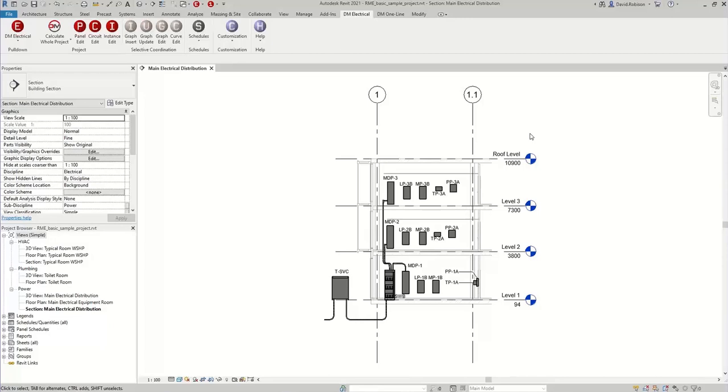So in the new release, we added a new feature to customize overcurrent protection settings for transformers. Previously, we would size the transformer overcurrent protection to be 125% of the transformer size. And we got a lot of feedback from a lot of customers that the sizes we were choosing were not what their company standards were. We went back and forth with a couple different customers and discovered that everyone has a slightly different standard, generally based on some sort of a calculation, but usually shading some numbers one way or another, or just choosing numbers that they happen to like better.